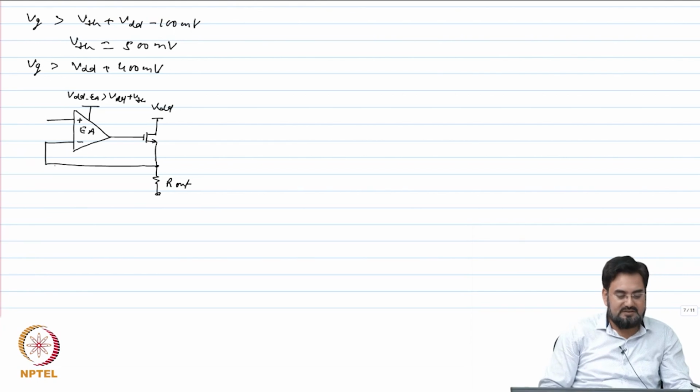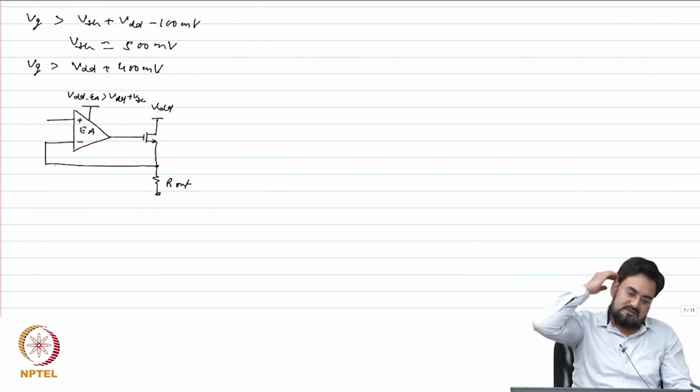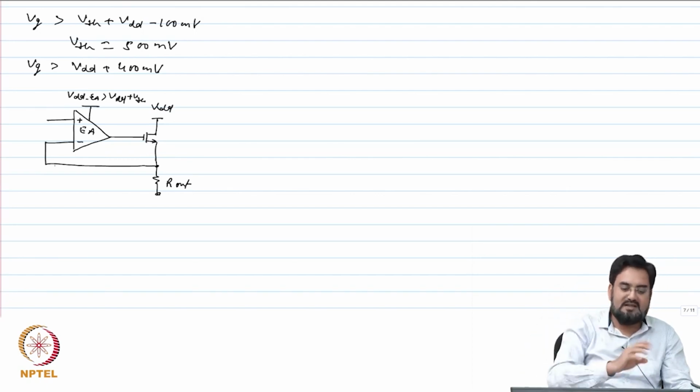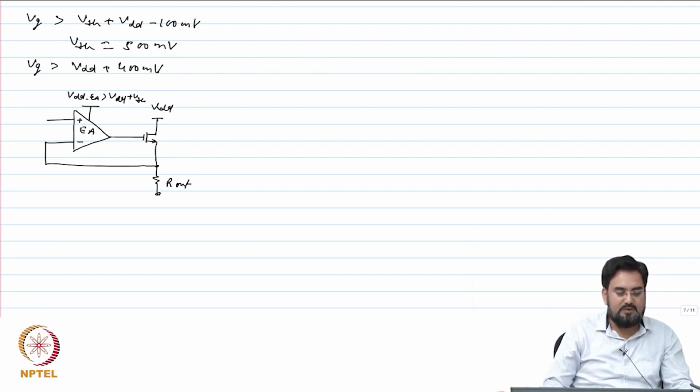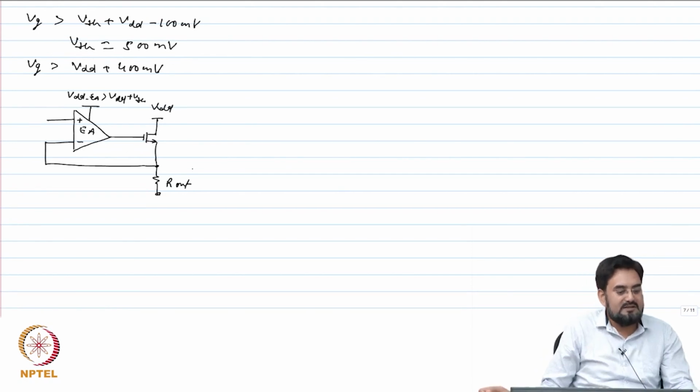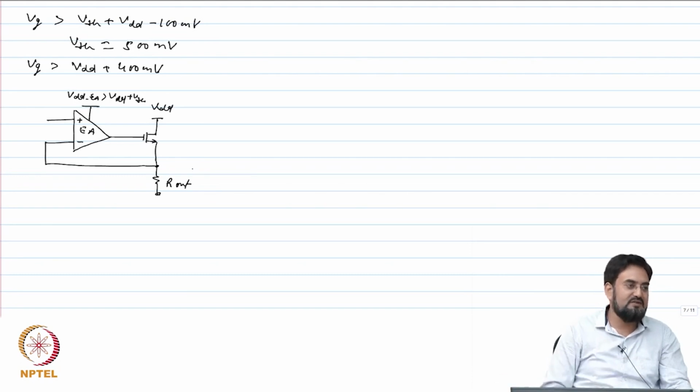And there are a lot of benefits actually with that. So gate cap is reduced. If you want to make the input pole dominant here, then you have to put obviously the larger cap at the output of this. If you want to make the output pole dominant, then again your output impedance you are looking at is 1 over GM now. So you may require to put a larger output cap also. So this may be quite useful if you want to drive a very large output cap. Okay.